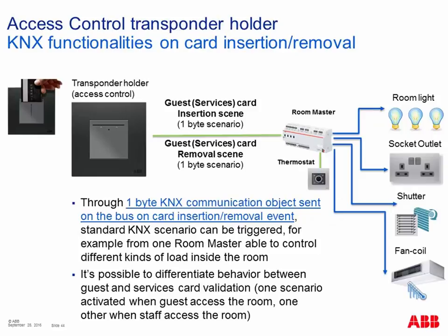The next slide shows the same functionality, so the same possibility to have a notification when the guest or service card is inserted or removed from the card holder, but in this case a 1 bit is not sent, but a 1 byte object is sent. For example, in this case the telegram is sent to a KNX device like the room master, and then the room master can control different loads like heating and cooling, shutter, socket outlet, lighting, and so on.